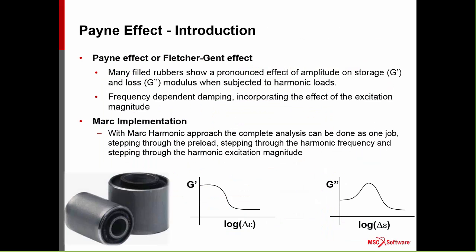Okay, let's talk about nonlinear analysis. And the first material model I want to talk about is what's known as the Payne effect for modeling effectively the viscoelastic behavior of rubber and elastomers, where we have not only a frequency-dependent damping, but we also have a damping that's dependent upon the amplitude of the excitation.